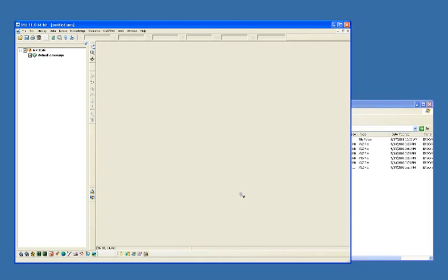And so sometimes we've seen that a user using the 32-bit version of SMS may not have access to all of the simulation that they actually ran. It'll stop after a certain period of time. And the only way around that is to either not output so much or to use a 64-bit version of the SMS.